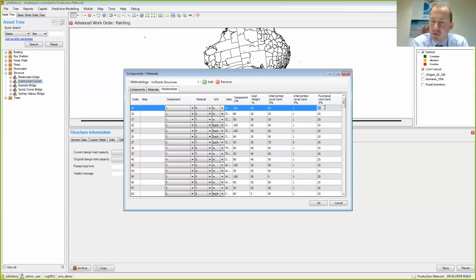It's still in service today, but it's past the point of when you would have normally liked to intervene according to the criteria that we'd put in here, which kind of makes sense. You don't really want to see a whole lot of corroded reinforcement and then try and fix it. You want to get in before then if you can. But once it's there, does it mean that the structure can't be used anymore? Well, not necessarily. And that'll depend on what limit you want to use for it. Hopefully that's answered that question.